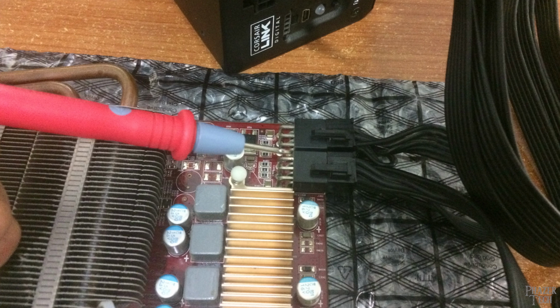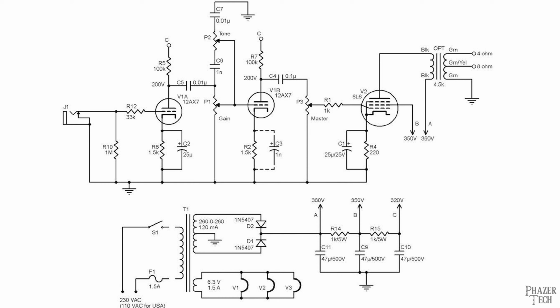There's a few other things you can do to debug the circuit before moving on, but usually, this is where you'll want to start measuring voltages around the circuit to determine where the issue is. But how do you know what the voltages are supposed to be? Well, you'll need to get a schematic for the circuit you're looking at and work out the KCL and KVL equations for it. Then compare these values to the values you measured.